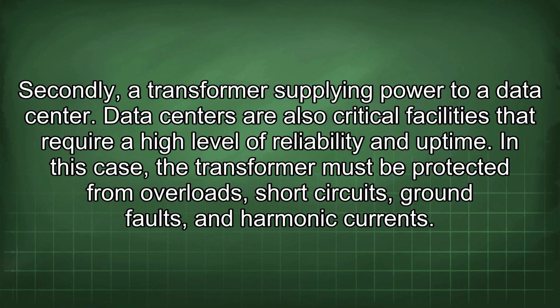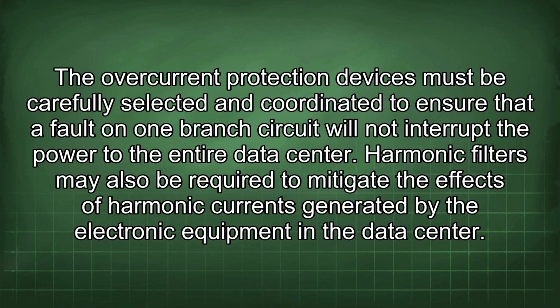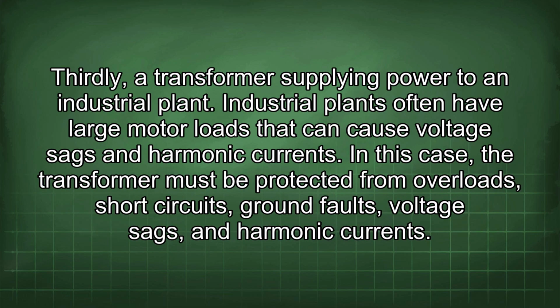Secondly, a transformer supplying power to a data center. Data centers are also critical facilities that require a high level of reliability and uptime. In this case, the transformer must be protected from overloads, short circuits, ground faults, and harmonic currents. The overcurrent protection devices must be carefully selected and coordinated to ensure that a fault on one branch circuit will not interrupt the power to the entire data center. Harmonic filters may also be required to mitigate the effects of harmonic currents generated by the electronic equipment in the data center.